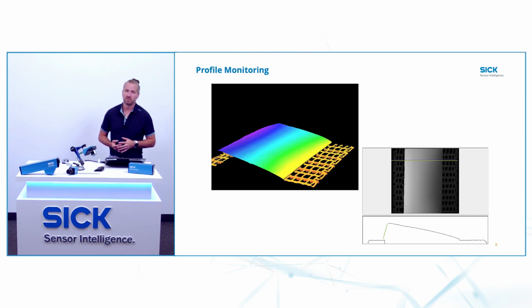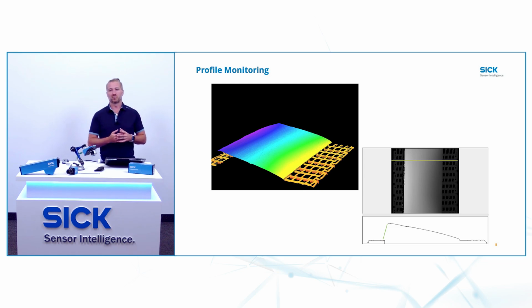Further, we have profile monitoring. As the triangulation cameras are building up these 3D profiles, we can start to do analysis on the profiles themselves: what's the slope, what's the contours. So a lot of higher-end dimensional work would be a lot more difficult to do in the 2D sense, because you're talking about external lighting and trying to pull out profiles. So we're really starting to get into the power of 3D in tire manufacturing and assembly, because of that low contrast, and because of the high tolerances and measurements that are needed.